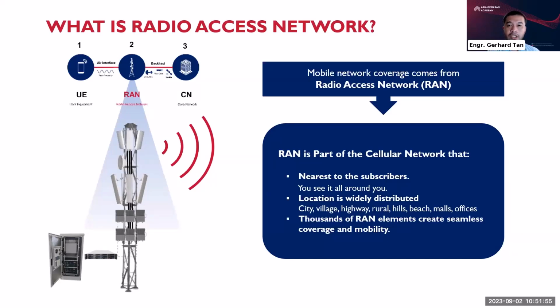What is the configuration of the site? What is the technology of the site that you will be building in that target coverage area or location where you want to build your site? Of course, you have your coverage planning. What is the sector? Assuming that you're building a 3-sector site, or at maximum 4-sector, especially in highly dense areas. Then you need to determine how high the antenna is, based on how far you would want to cover. Geometry.